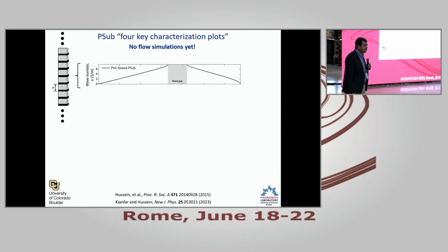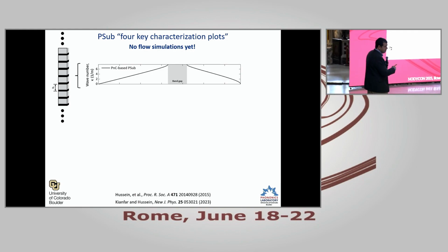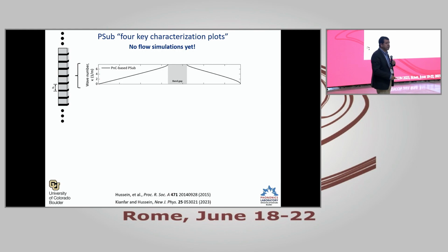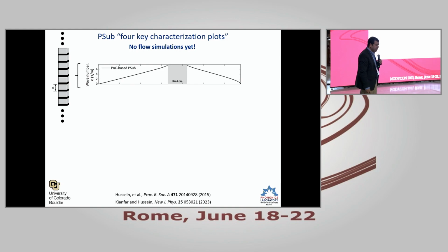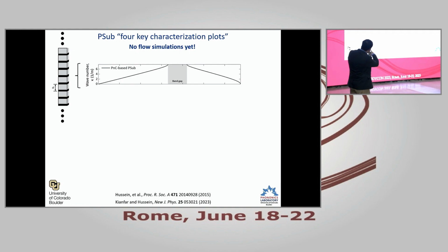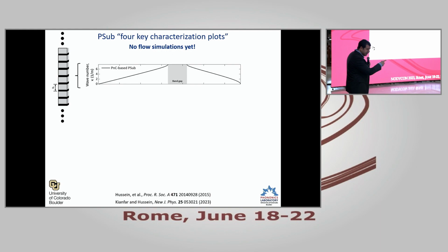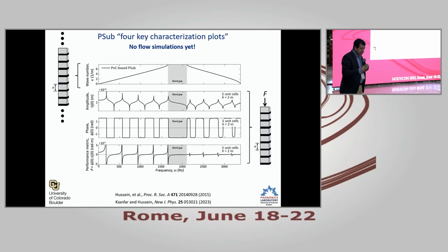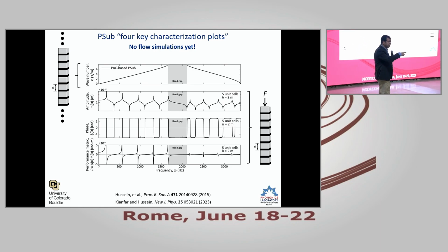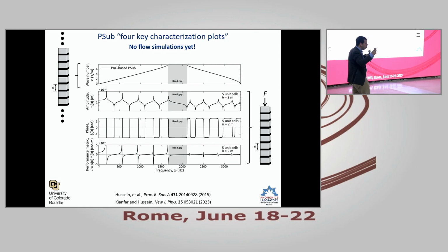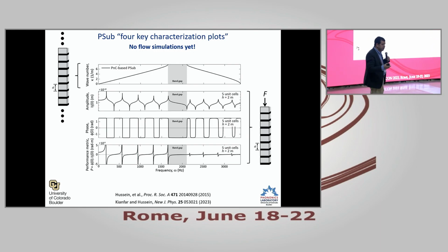So we start by looking at a single unit cell in this periodic structure. We call this a phononic crystal. And you can plot the dispersion curve. So this is wave number versus frequency, and the x-axis here is the frequency. You can see a band gap, a range of frequencies where waves cannot propagate, and the black lines represent propagating modes. And I should say that everything is linear here. Now, on the other hand, if we truncate that structure and turn it into a finite structure, it's no longer a material, it's no longer an infinite media, it emits vibrations rather than waves.